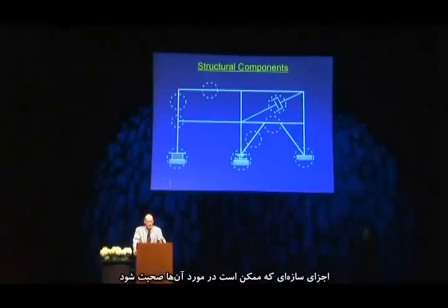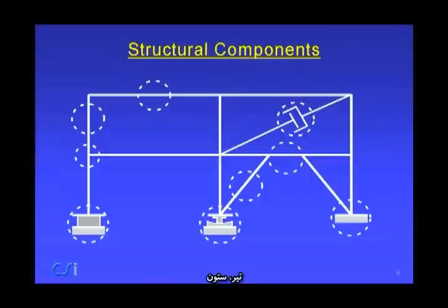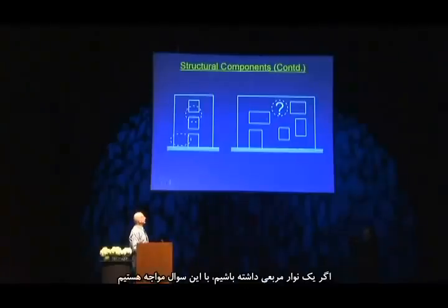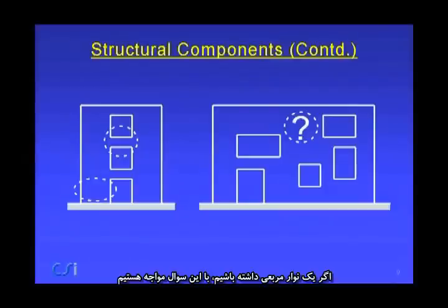The types of structural components we might be talking about: a beam, a column, a beam-to-column connection, a viscous damper, a diagonal brace, a shear link in an eccentrically braced frame, a friction pendulum isolator, a rubber type isolator, maybe the foundation, components of many different types. If we look at a wall, we've got a pier, a beam. If we have a rather squat wall with odd-shaped openings, we run into issues. Well, are there really components in here? What would the component be? But we still would have to somehow come up with an answer to that question.